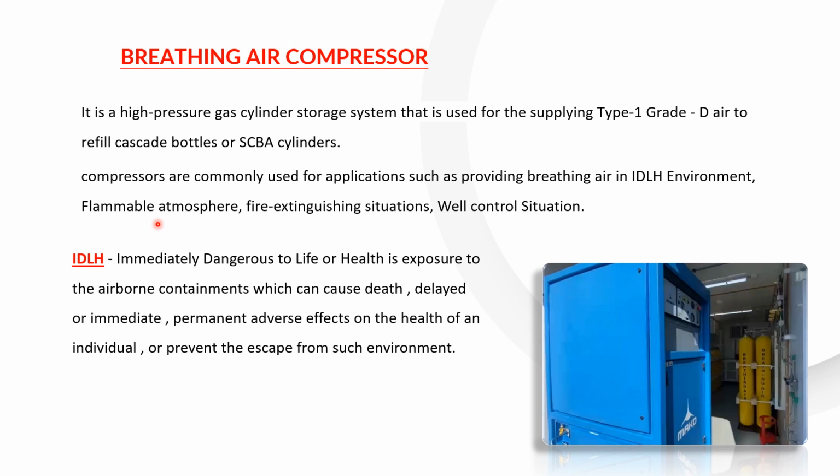Okay, and other hazardous gases are available there, for example methane in the atmosphere. So that is an IDLH environment. So what is IDLH? IDLH stands for immediately dangerous to life or health. It is exposure to airborne contaminants which can cause death, either delayed or immediate, permanent adverse effects on the health of an individual, or prevent escape from such an environment.